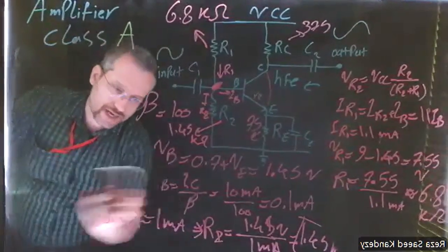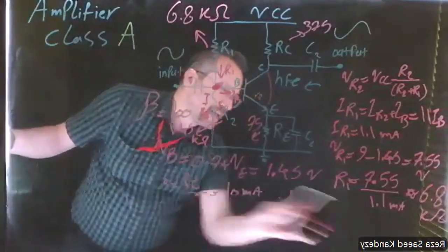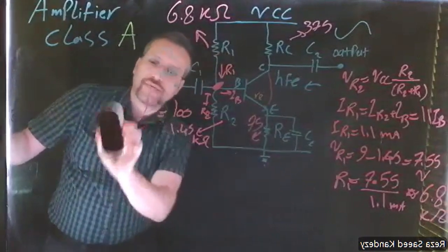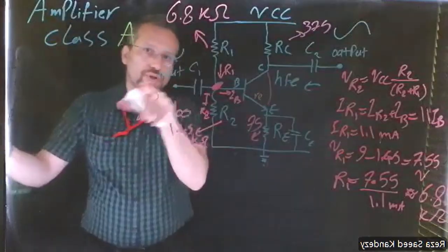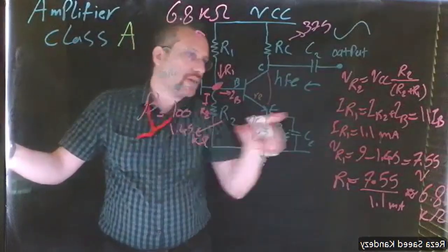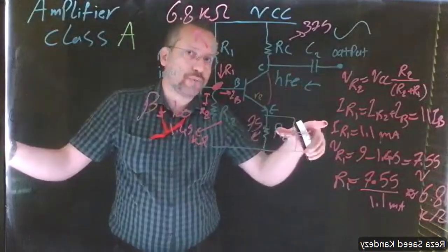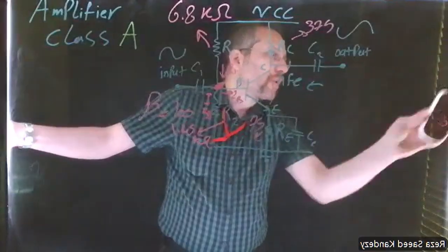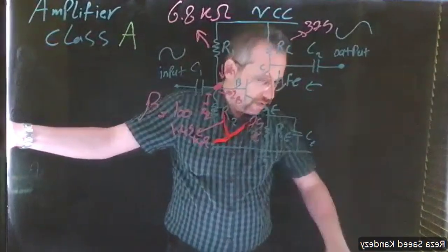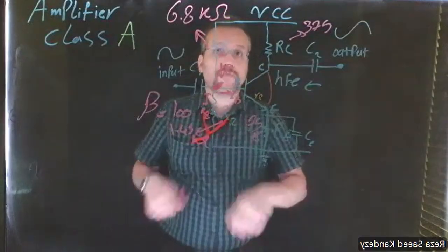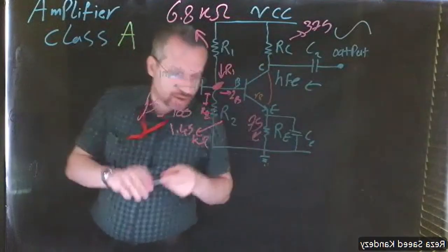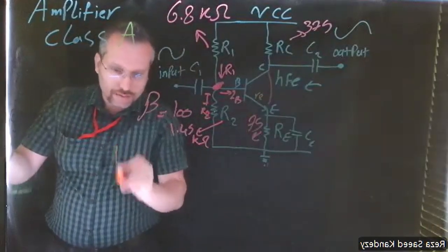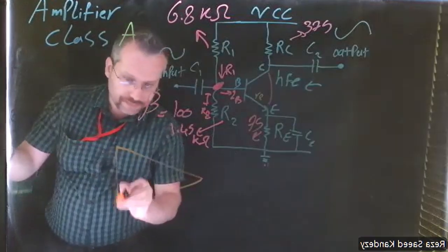This is actually gonna be very helpful to understand what we actually see, because all these calculations that we did, there is no input circuit here, there is no input, and there is no load or output here. So when we add those things, we're gonna see different gain because it's changed the circuit. Now, how can we actually model our amplifier?